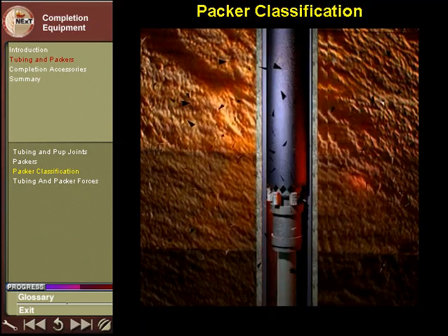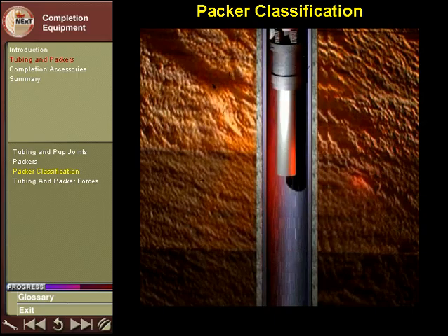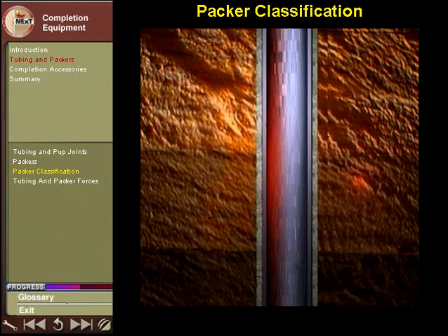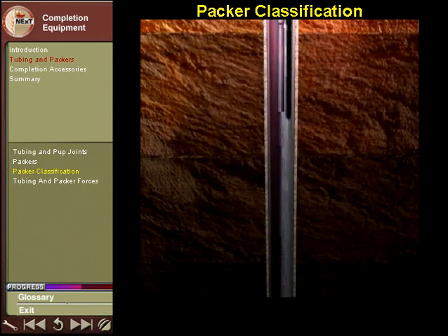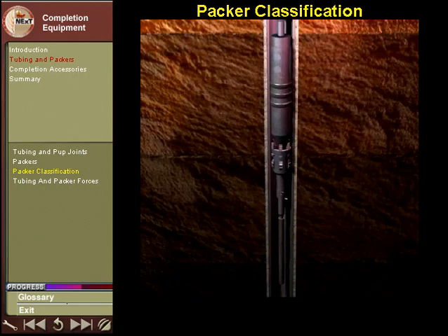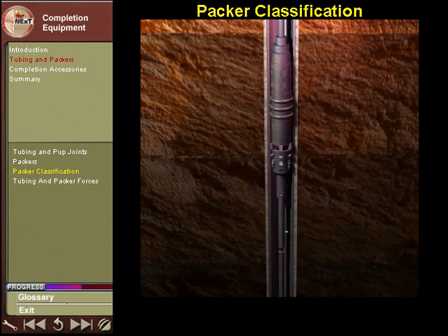The permanent packer itself needs to be drilled to pieces, a practice known as milling, to be removed from the wellbore. Retrievable packers, on the other hand, can be removed by tubing or a work string, repaired at the surface, and then reused. This allows for equipment changes and repositioning.